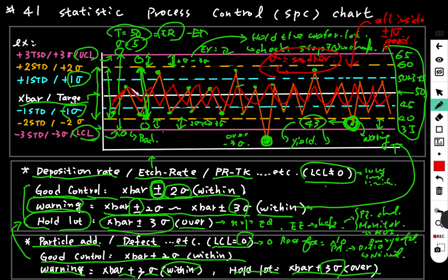So if your value is under control very perfectly, you've got to tighten your sigma value to make the scale smaller. Then you can see the edge in more detail, but it becomes more difficult to maintain your good performance with the SPC chart. This is the 1 sigma function. I shall see you next time.